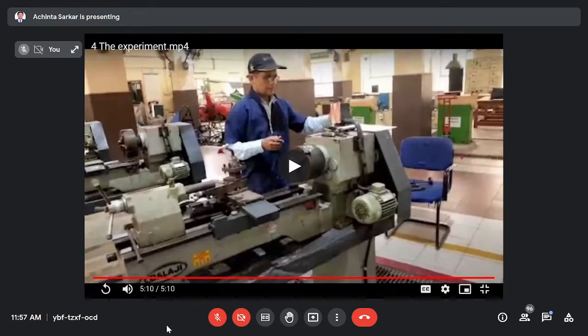If the job moves eccentrically, it will be too difficult to cut the material. On one side or in one axis it will cut more material, and on the opposite side it will cut very little, because the job itself is held eccentrically. So after machining we will get an eccentric job, not a concentric job.